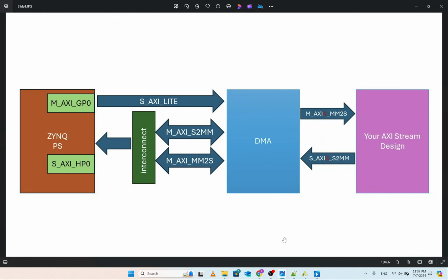I will try my best to explain how to create a hardware design that accelerates some function using a simple design for a simple adder. And we're going to accelerate these functions using the PYNQ board, which is a Xilinx board. To be aware, Xilinx boards use the AXI protocol a lot to transfer data from the processing system to the programmable logic back and forth.